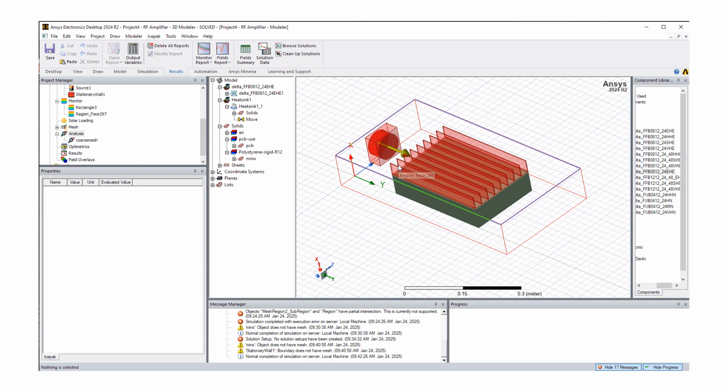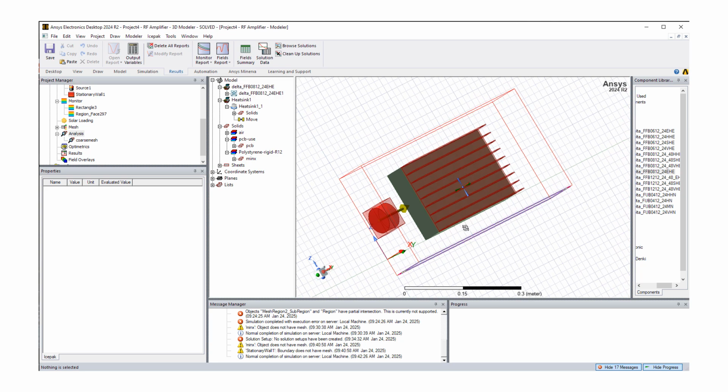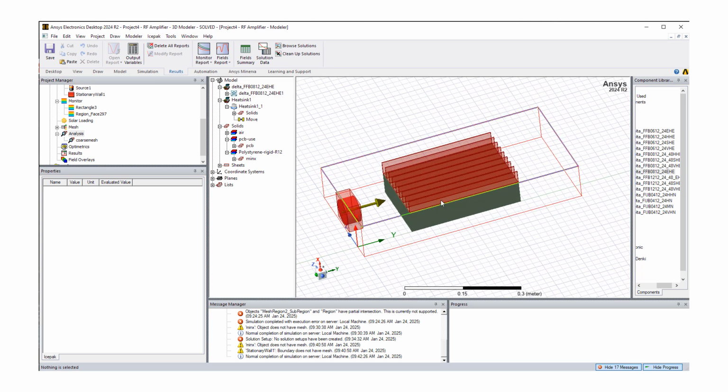To fix this, typically when you have a problem, a lot of times it's in the meshing, it's in the setup. And in this case, we have some indicators here, some warnings in our log window at the center bottom. So let's heed these warnings, do a remesh, and recalculate our solution.